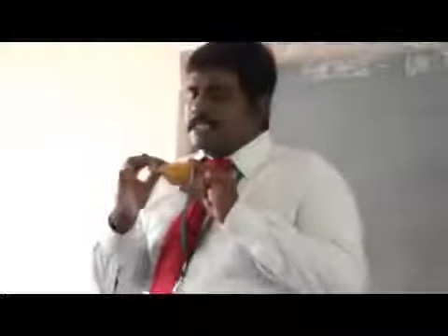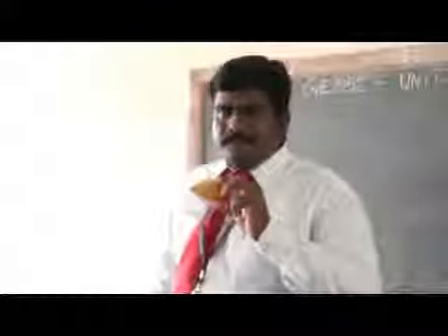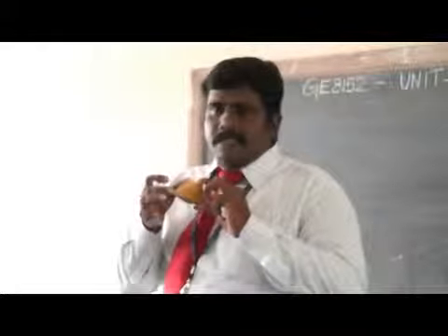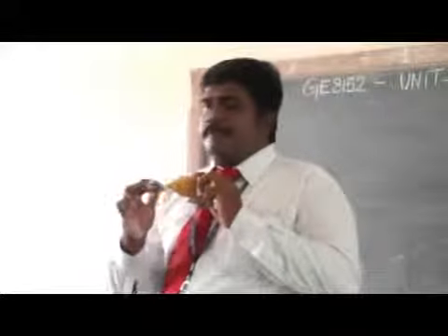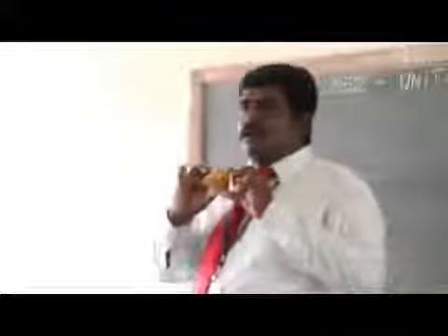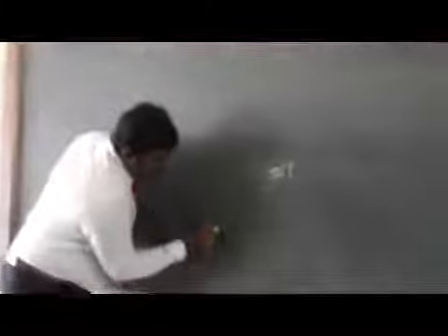4 slant edges. So these four slant edges, it seems to be starting from this apex and ending at what? The base corners. Am I right or not? So now, when you observe this, these slant edges would be visible or not? Is it visible? But not to the true length, but of diminished length. But there it seems to be a line which connects this base corners and the apex. Okay, so when you draw the pyramid, you have to draw the slant edges also.